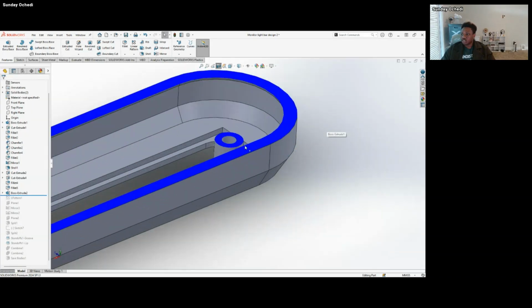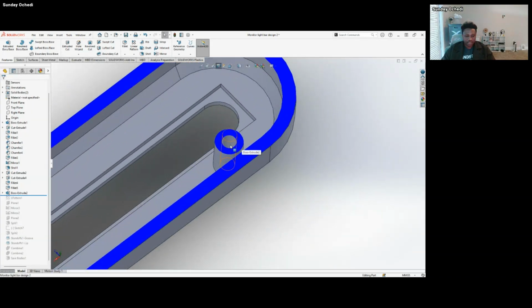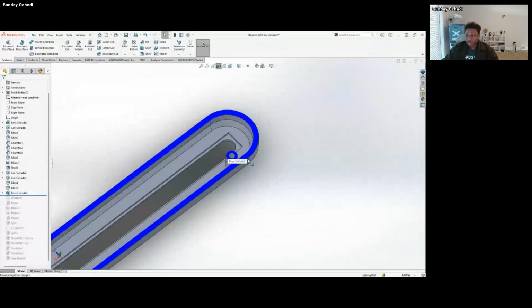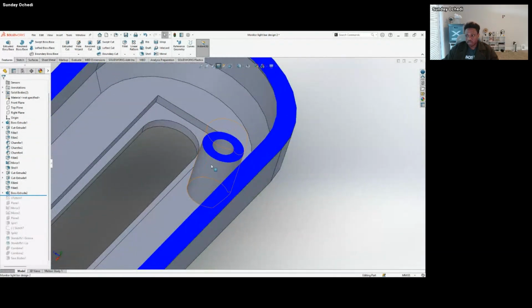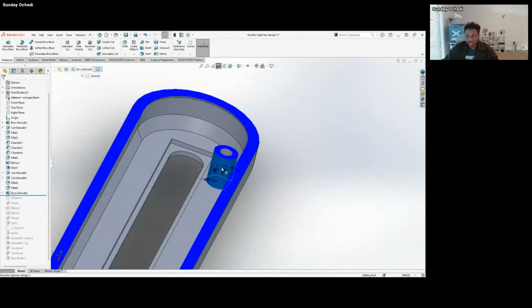And to use the screw you have to have somewhere they can fit in. So there are self-tapping screws, and there are screws that need somewhere to go in. Self-tapping screws can just go into plastic, and you forcefully thread them through the plastic. But I want to use the normal screw, and to use that I need something called a threaded insert, and put them in the place where the thread is supposed to go, and then I can have the screw put in there. And to do that, I have to create places for this threaded insert, which is this.